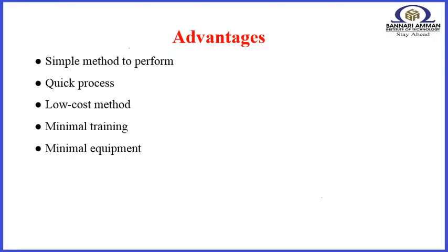Advantages of visual inspection. It can be a very simple but effective test to perform and often does not need expensive equipment. Experienced operators and advanced equipment make it possible for visual inspection to be very sensitive. It allows discontinuities to be seen and not be just a blip on the screen. Many different surface breaking discontinuities can be found. Training and experience times can be short. Virtually any component can be examined anywhere on the surface.